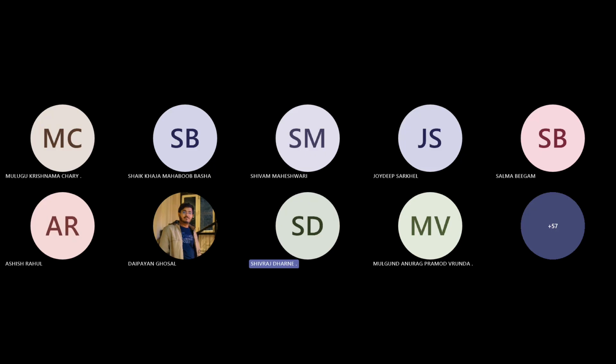So then you have to have operational strategy. Operational strategy means, just now today we learned monitoring and control, right? So environmental sensors, building management system is also another thing, and data center infrastructure management, DCIM integration, right? So there will be some alert threshold, escalation metrics, incident response time, all that, right? And then today also we talked about maintenance, right?